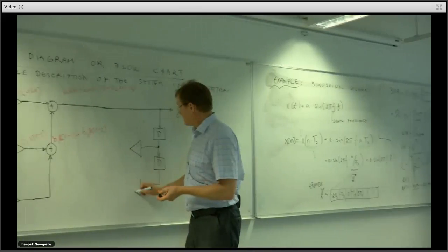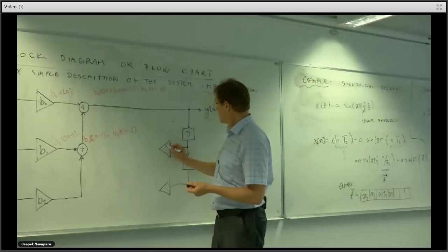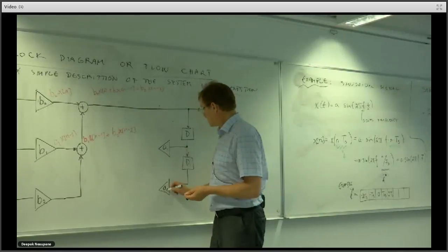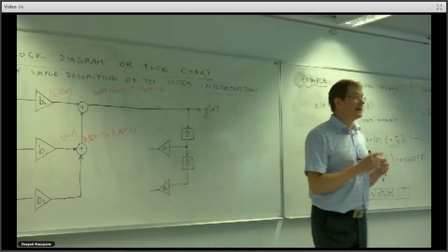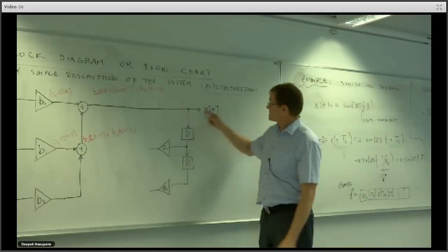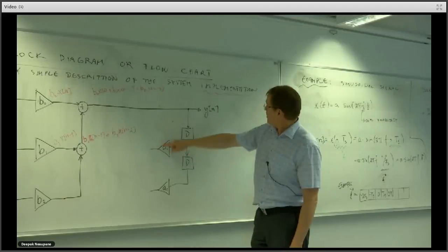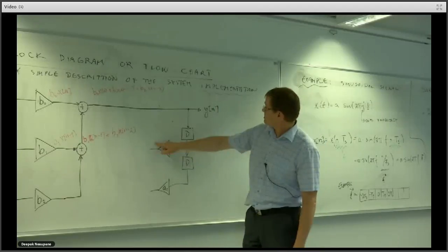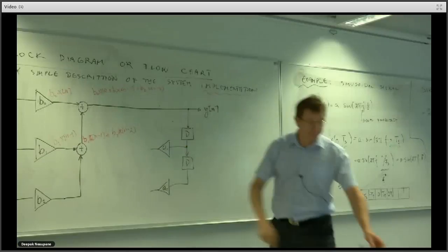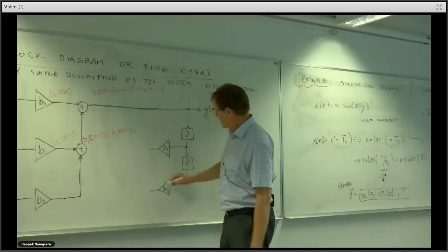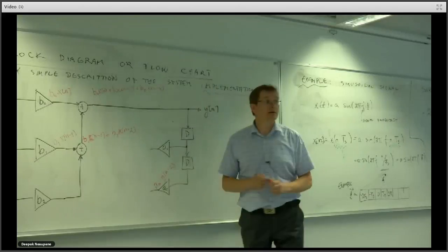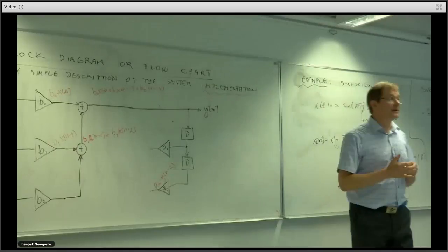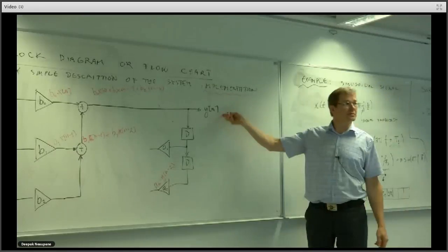You fundamentally put here another blocks for scaling the signal. So that would be after that a1 times yn minus 1 here. Or I'll just mark that one. a2 times yn minus 2. So it's feedback taken from the memory of the output. Okay.